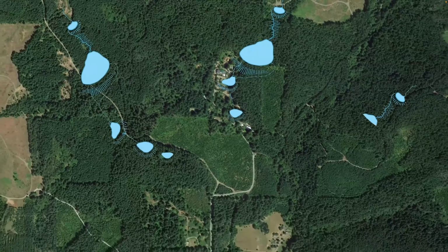The other thing that we really want to look for is the depth to bedrock. In a lot of cases, the soil depth may be just a matter of feet before it gives way to fractured bedrock and then actual bedrock. And if that's the case, that's essentially going to limit the depth of your pond. So these are some really important initial notes to make.